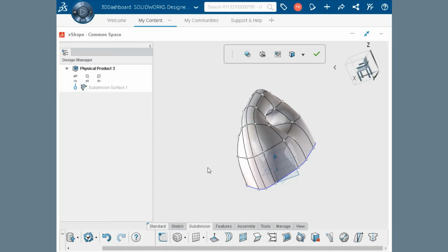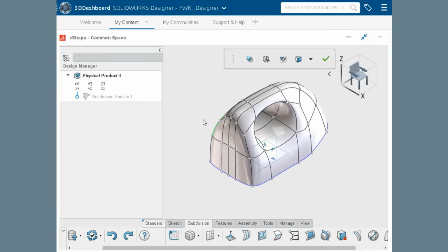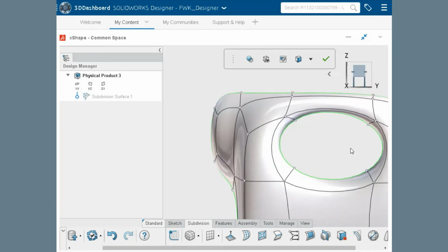After making a few more adjustments, we'll use Extrude in a different way with a different toolbar. Control select the two rear faces and then click Extrude from the Quick Command toolbar. And extrusion, combining the two faces, is added. Here's another great option, aligning a set of vertices to align.